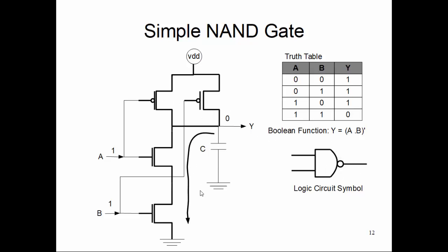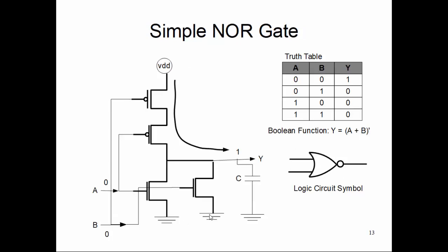notion, that NOR gate. NOR gate is just, you can say, a mirror image of the NAND gate, in the sense that here in this case your NMOS are connected in parallel, then PMOS is connected in a stack configuration or in series. So PMOS serial connection stacked with NMOS parallel connection, and it works just the reverse way of the NAND gate.